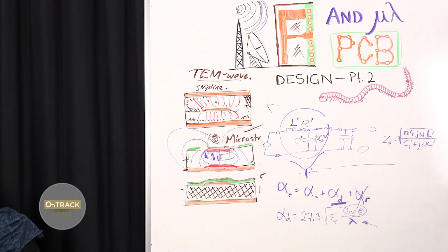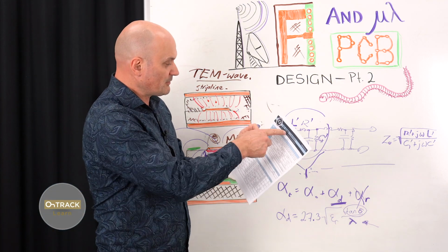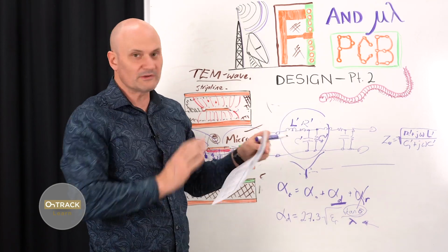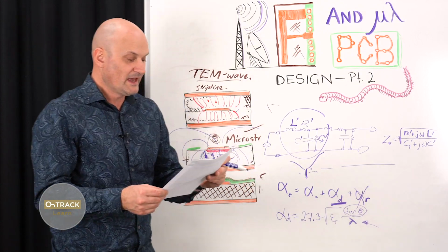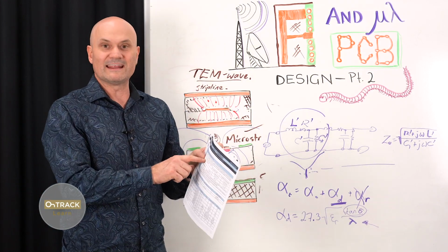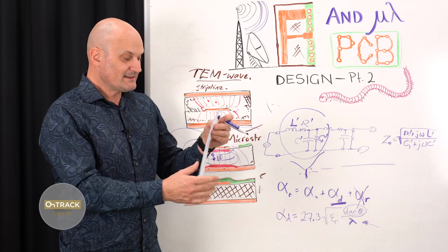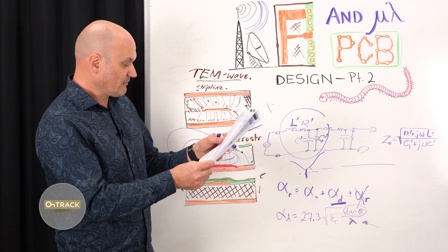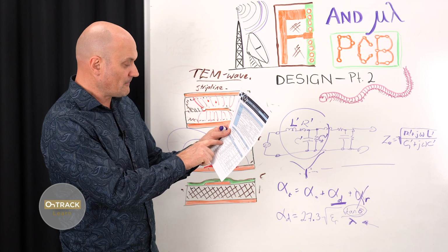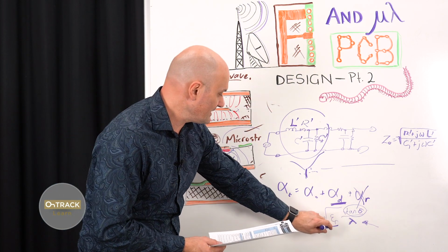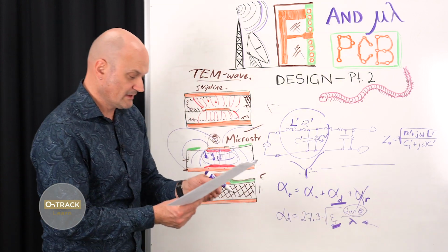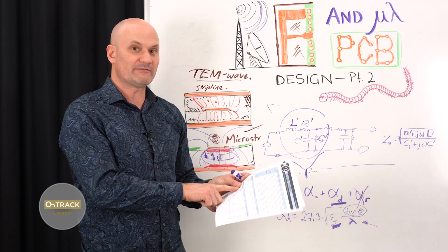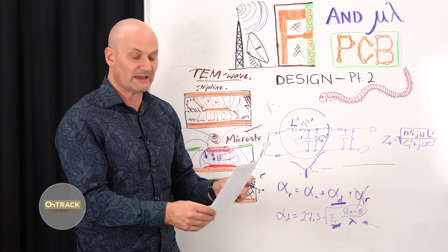So I have, for example, a standard, this one's from the Gund company, but this is a standard FR4 data sheet. FR4 is the most common material used today in PCBs, and the grade FR4 is actually an NEMA standard, and they all pretty much comply to this exact same characteristics. So for typical FR4, the permittivity, epsilon sub r, is measured almost always at only 1 megahertz. So it may be very different. It can be frequency dependent, and in fact it typically is.